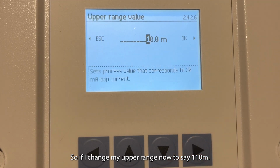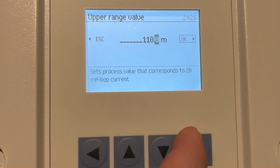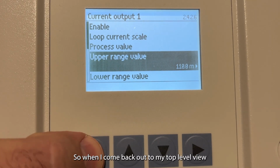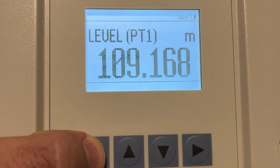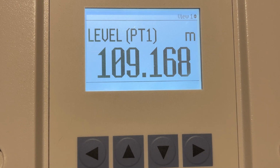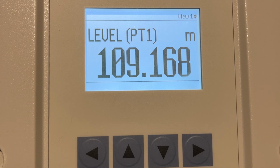So if I change my upper range now to, say, 110 meters, that clears my diagnostic. So when I come back out to my top level view, now I'm reading 109 meters, before I was just reading 9 meters, and say I've got a reference to sea level now. Now, the one thing to be aware of is that does affect the amount of resolution you have on your milliamp output, but it is a true reading as required versus sea level or some other reference point.